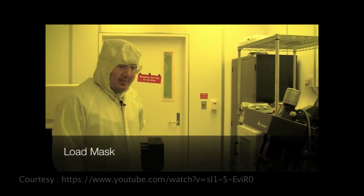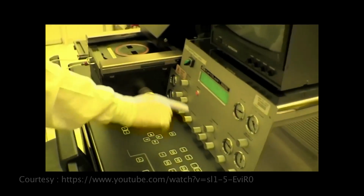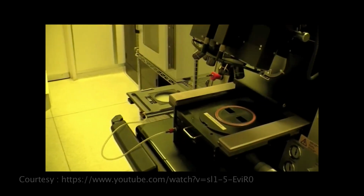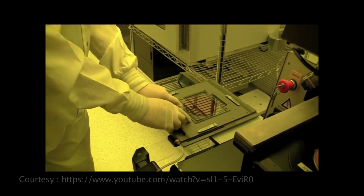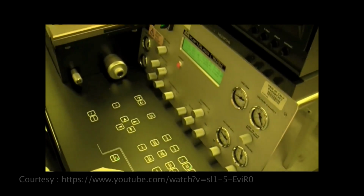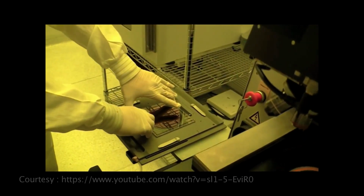What we're going to do now is load the mask. So how do we load the mask? We press the button called change mask on the screen. So when you hit change mask, you're ready to load the mask. So we put it in here. So you load your mask in here by lifting this clip here and putting it in. And when it's in nice, you hit this button called enter, and you can toggle the vacuum. So right now the vacuum is off. When you press enter, now the vacuum is on. And when you come back, you can see that it's vacuumed in and it's stuck pretty well.